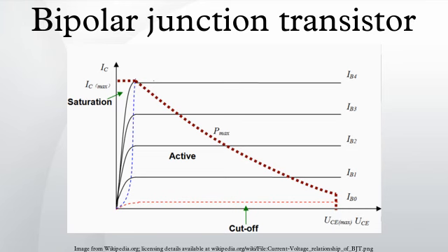The parameter hoe usually corresponds to the output admittance of a bipolar transistor and has to be inverted to convert it to an impedance. As shown, the h parameters have lowercase subscripts and hence signify AC conditions or analyses. For DC conditions they are specified in uppercase. For the CE topology, an approximate h-parameter model is commonly used, which further simplifies the circuit analysis. For this, the hoe and hre parameters are neglected.